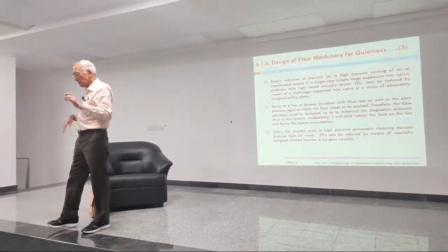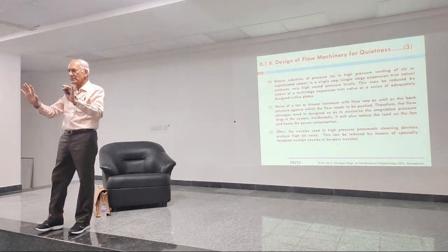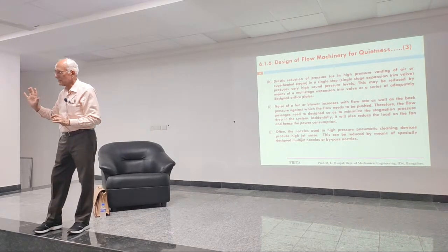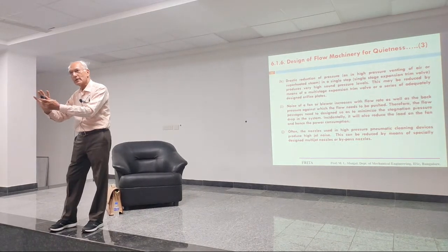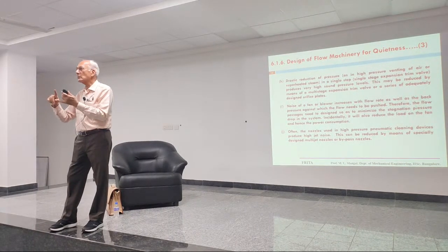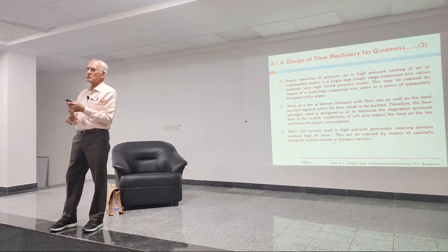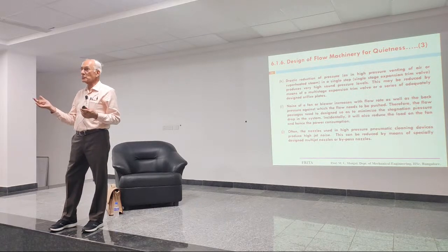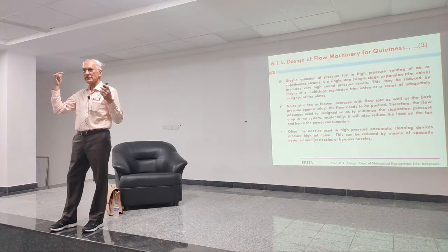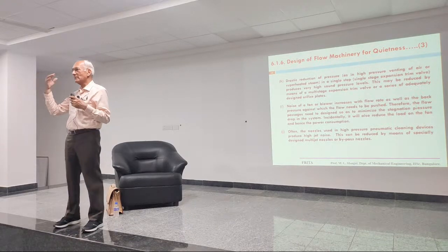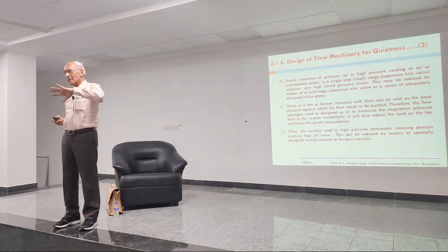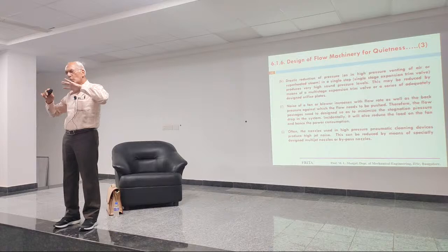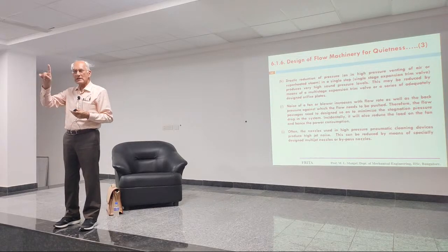You don't have to go too much deeper. All I'm telling you is the fan is trying to push some air, and if it has to push against higher back pressure, obviously it will spend more power and also produce much more noise. So you are losing both ways. The efficiency is reduced, at the same time noise is increased. And in fact, you will find most of the times a quieter machine is also a more efficient machine.